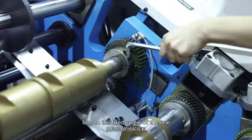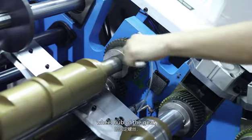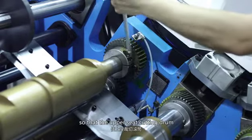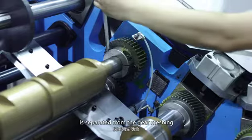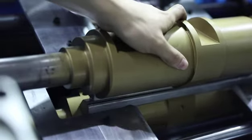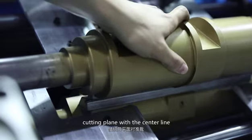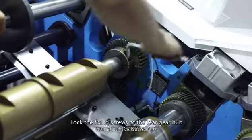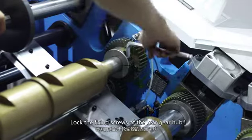Loosen the fixed screw of the rear wheel hub of the gear so that the upper seat cutting drum is separated from the gear meshing. Manually turn the roller of the upper seat to align the cutting plane with the center line of the cutting module opening. Lock the fixing screws of the rear gear hub.